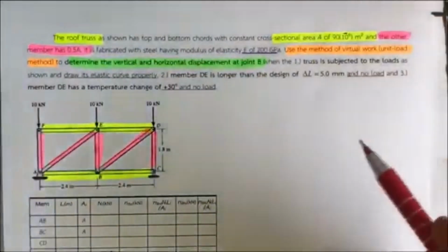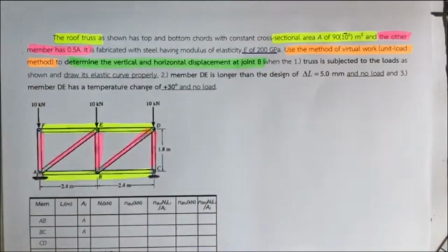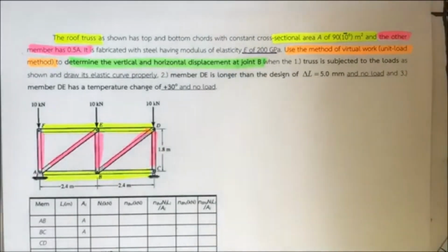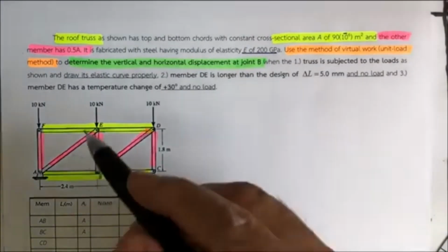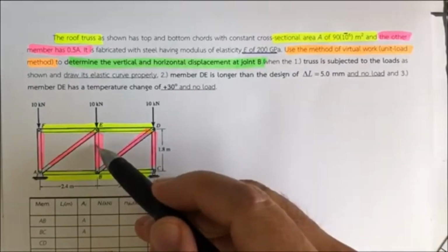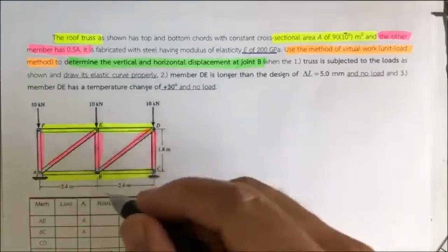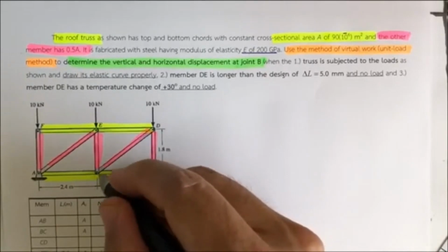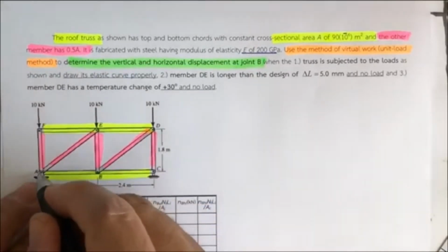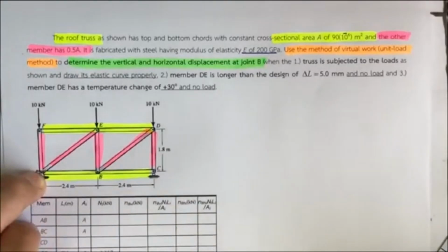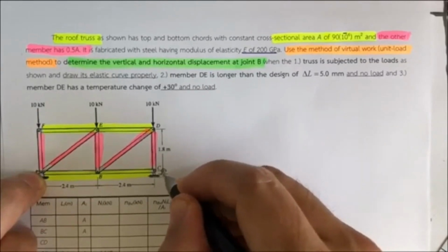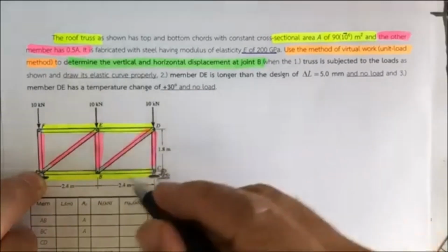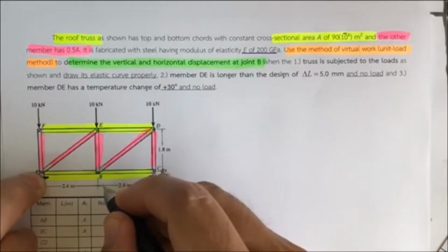They ask us to determine the deflection at B. Before we go further, let's try to understand what happens. When this one is pushed here, our beam is going to deflect downward, right? And since this one cannot move horizontally or vertically, only this one can move.